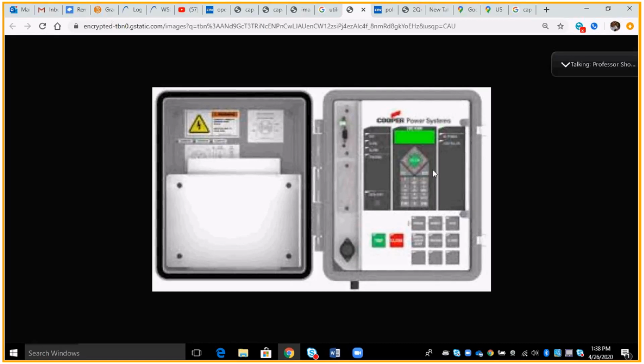There's some other different settings that are going on in here, but the trip and close is the majority of what you're going to use all the time. And to be able to open it, you're going to have to trip it open. Tripping open, I've got no problem with. You can be right at the control panel to do that as you're actually de-energizing something. The close is where you need to be safe and watch what you're doing here.